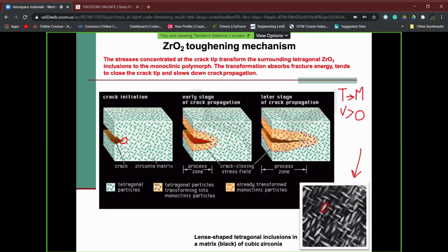And if we start with pure zirconia, where the fracture toughness of the material is something again about 3.5 megapascal per square meter, in the solution that we are going to describe by using a partially stabilized zirconia with 6 to 8% in weight of yttrium oxide, we can reach values of fracture toughness which are near, let me say, 13 or 15 megapascal per square meter, with a very relevant increase in fracture toughness of the material itself due to this transformation mechanism.